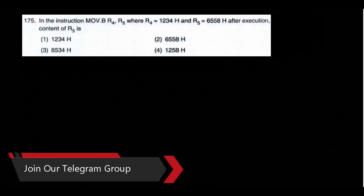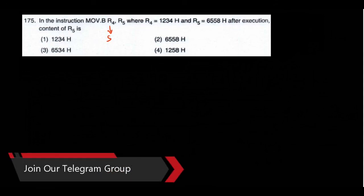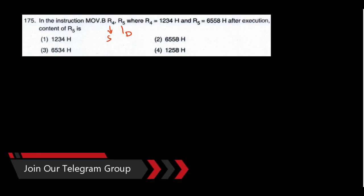In the instruction MOV.B R4, R5, this is the source and this is the destination. Once you execute it, whatever is in R4 will go to R5. So after execution, the content of R5 will be 1234H. From source to destination we have moved the data.